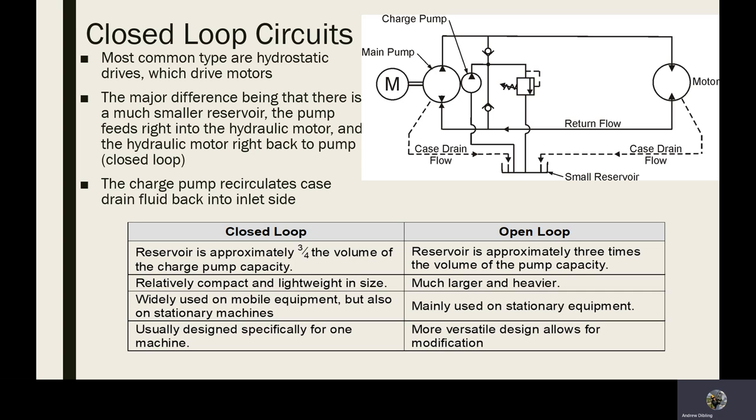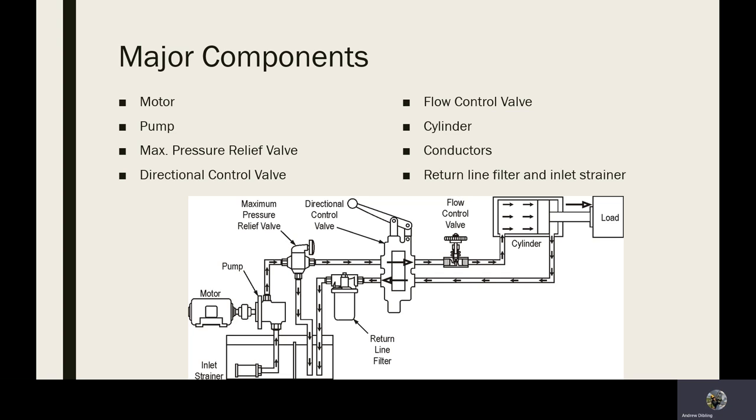If you've seen a ride-on lawnmower for large parks, this is the type of drive they have in them. You literally change the direction of the control valve to change the direction of the pump and the motor. Quite ingenious. Very simple system, very robust. Properly maintained, you will get hundreds of thousands of hours out of these machines.